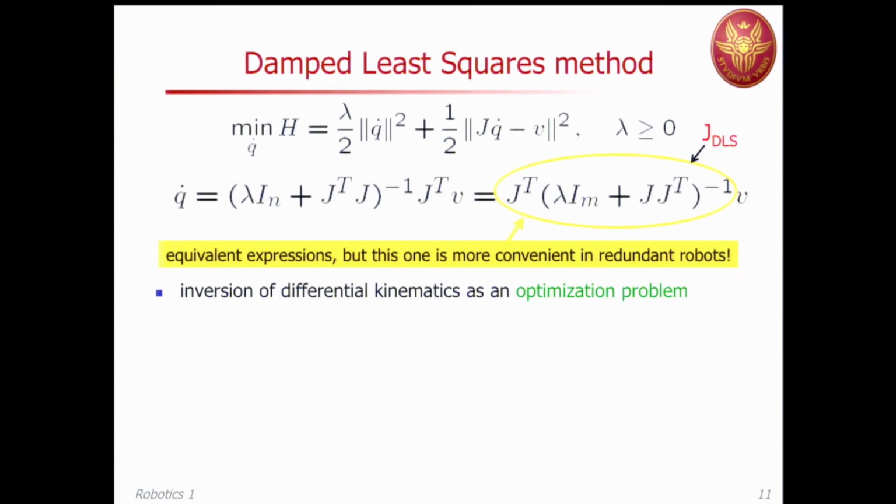And this is a handy solution, a first solution possible, which goes through doing some kind of damped least square. Instead of inverting my Jacobian matrix, I'm doing damped inversion. This is the terminology that is used. In fact, I reformulate the problem differently.